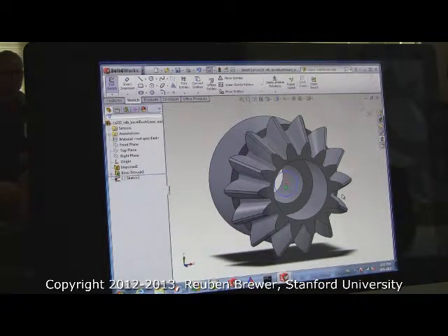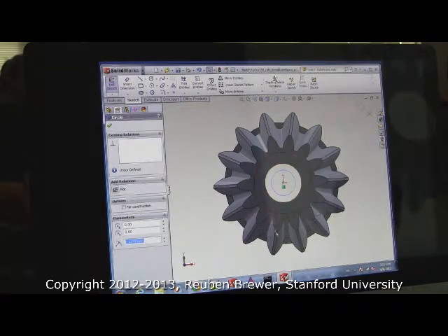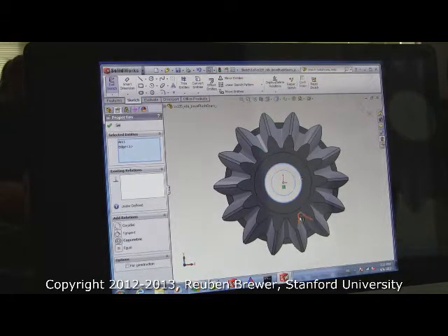Now I have to do two operations if I decide to change it to 9 millimeters. If instead I only ever set 8.1 or 9 or X once, and then every other time I base the other on that last dimension, it's much easier to update. So here's how we're going to do that. Click on the circle, and then click on the innermost circle of the actual part, and hold Control so you can get both of them.